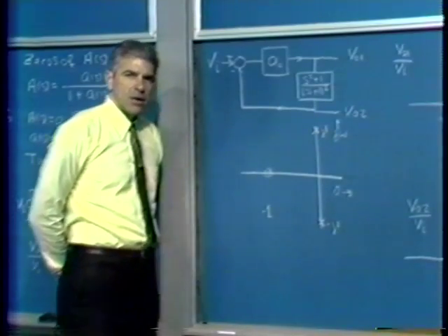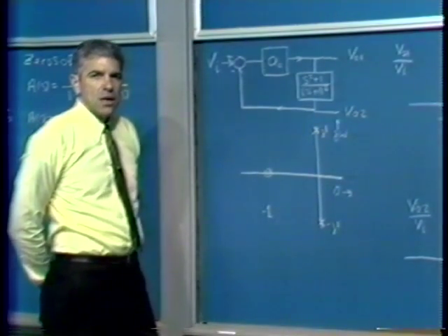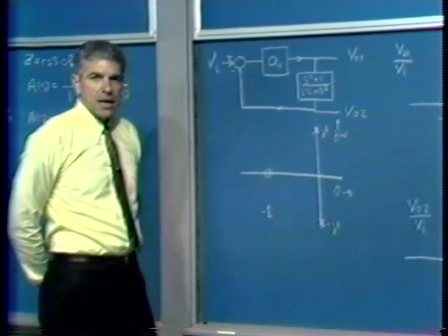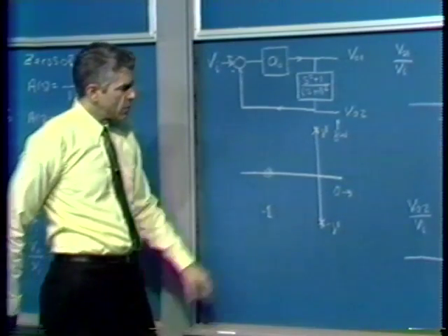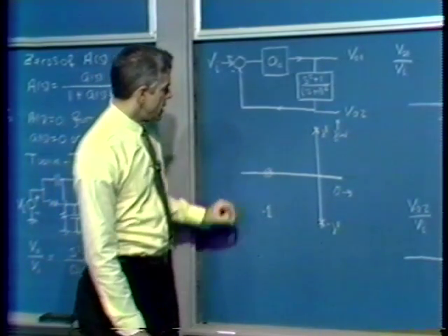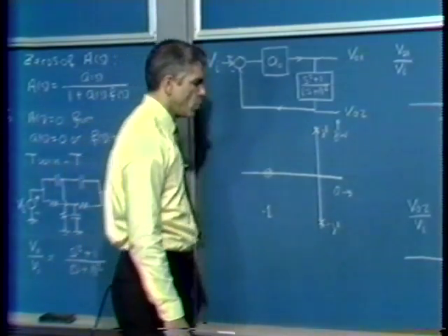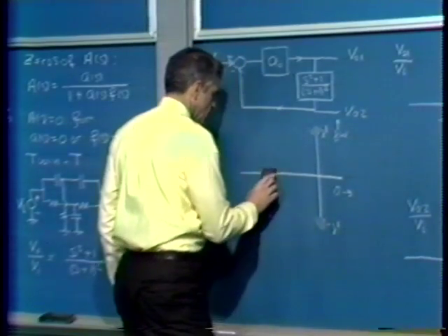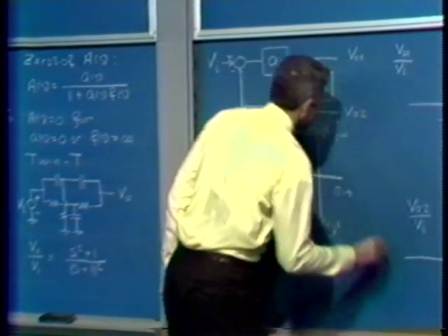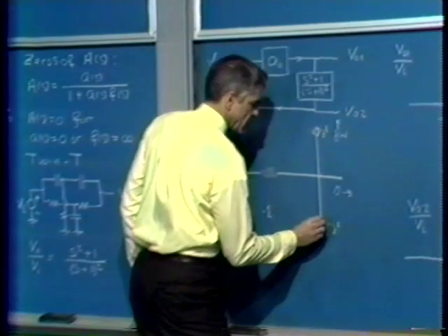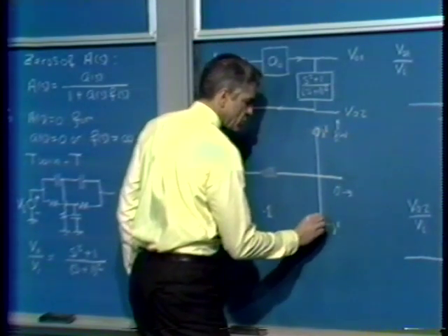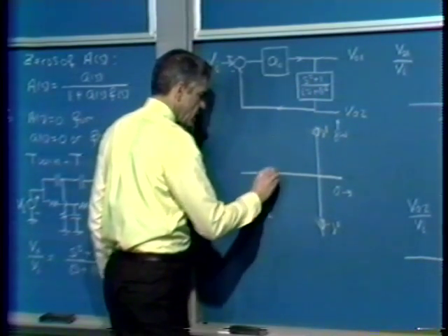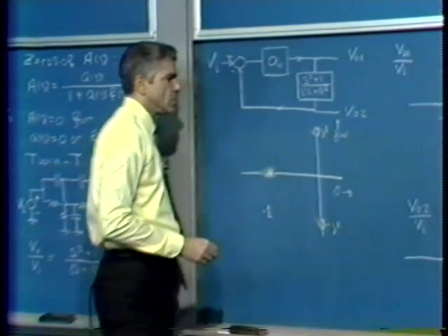And we can do that by our usual root locus techniques. The loop transmission has two zeros on the imaginary axis, a complex conjugate pair of zeros, of course. And so we start out with, I'm sorry, I have an error in this one. Let me indicate the zeros and poles correctly. We start out with two zeros in the loop transmission at s equals j plus and minus 1. And we have two poles in the loop transmission at s equals minus 1.